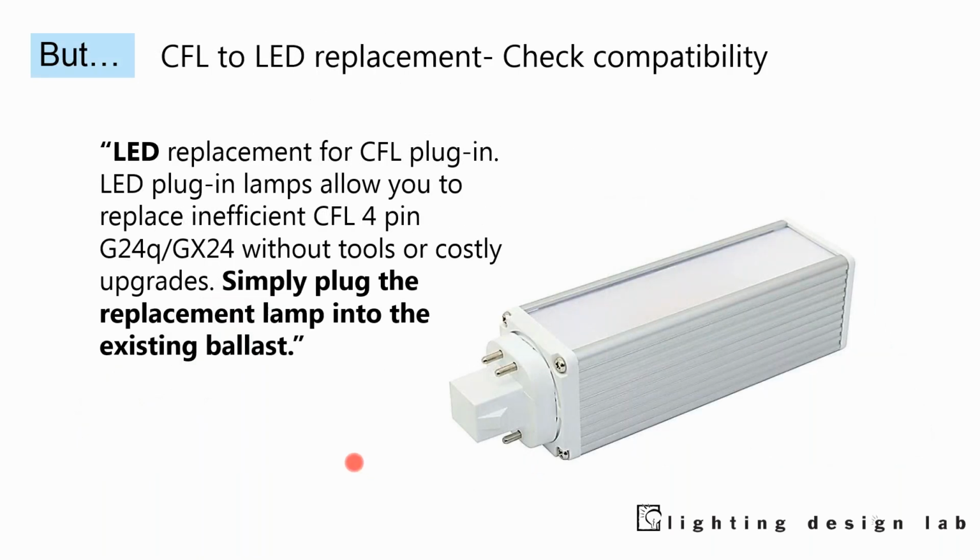But we see a lot of these LED retrofits. So here we have pin-based compact fluorescent and pin-based LED retrofits. But you need to be careful with those as well. Just like we had with the tubular LEDs, we still have problems with the compact fluorescent LED retrofits.